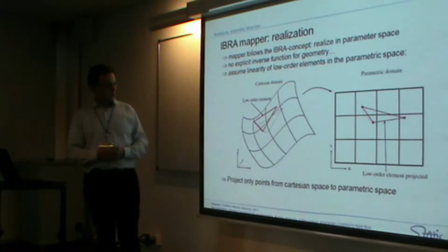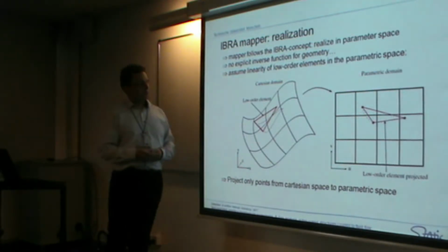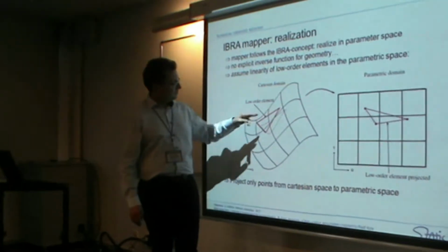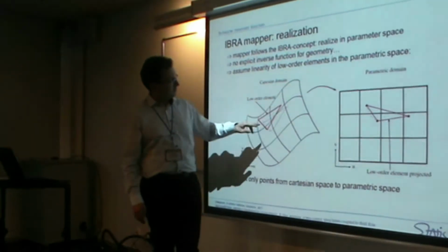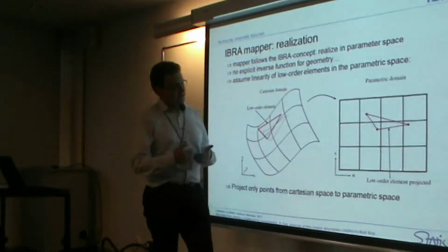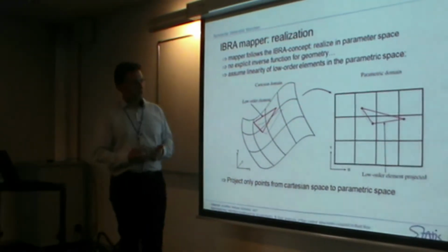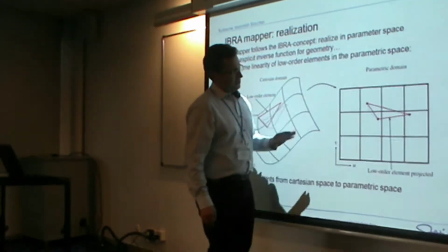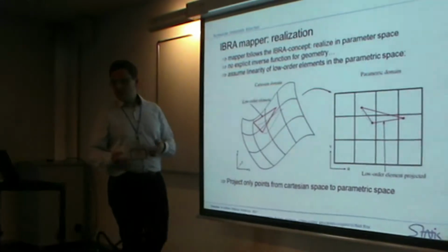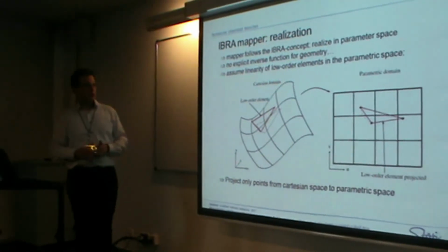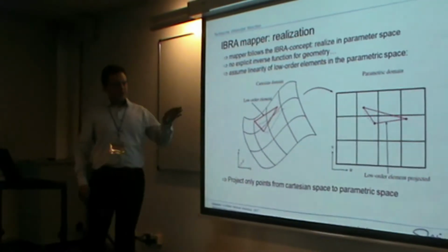A typical problem is that the mapping, when we want to do everything in parameter space, is not preserved: even if we have a triangle on top of that from the fluid mesh, for example, that will not be a triangle. We did investigations of that by even cutting these edges into smaller pieces, but in the end it turned out, in our case now, where we have LES simulations with fine surface meshes put on rather coarse structural discretizations, that this is doing a good job.